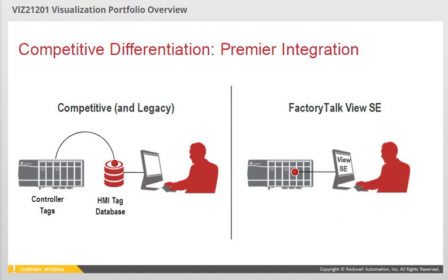In a FactoryTalk View SE solution, direct tag referencing allows users to browse for controllers and access controller tags directly. There are many advantages to this capability. It minimizes configuration errors. It also makes it easier to reuse displays between applications. As applications become larger and more complex, standardization becomes a very important topic.